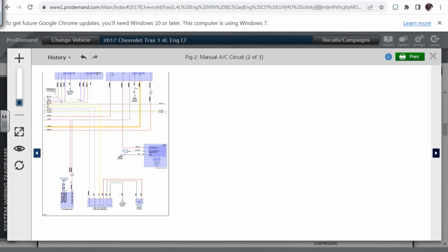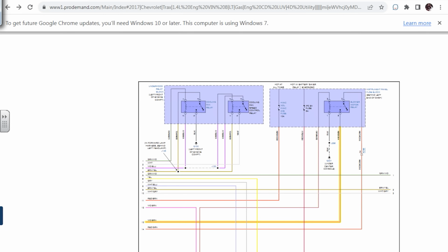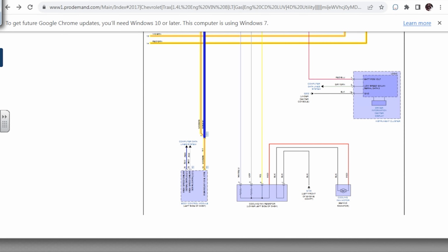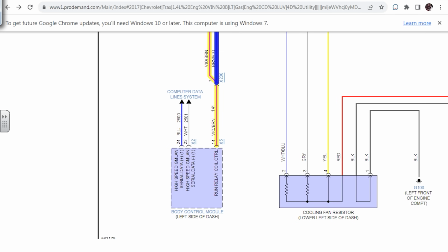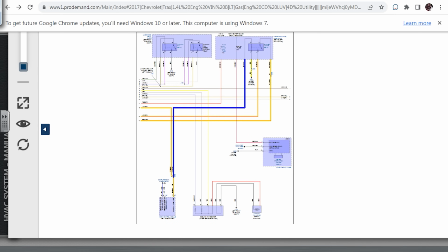That is relay controlled, right? So it goes to a relay. So there's a 40 amp fuse that feeds this side. It's back on the other page. And then the control side of the relay up here is externally grounded all the time. And that means this is a power side switch circuit. So where that goes is our control, and that is the BCM. The BCM then switches that relay on to provide power to the blower motor all the time. Like as soon as you turn the key on, I believe that would be active as soon as you turn the key on, pretty sure.